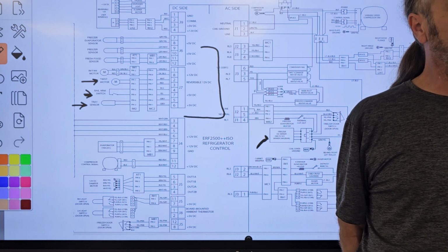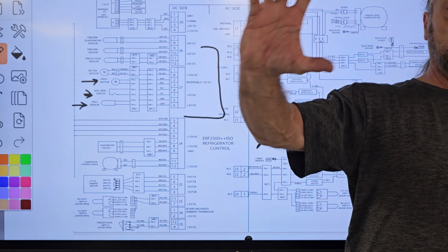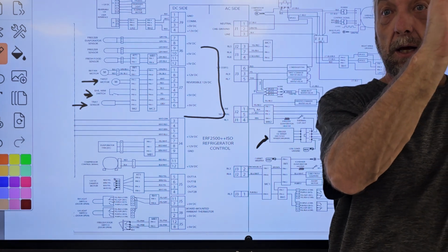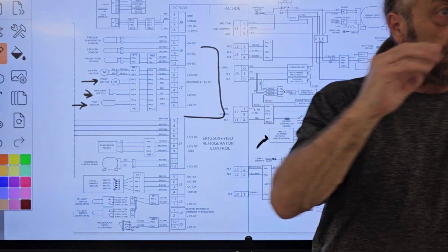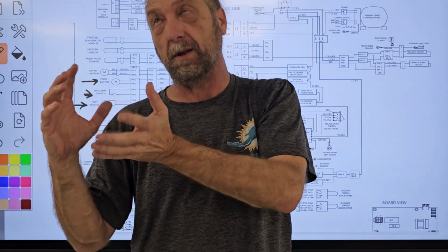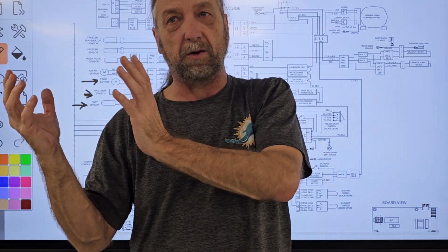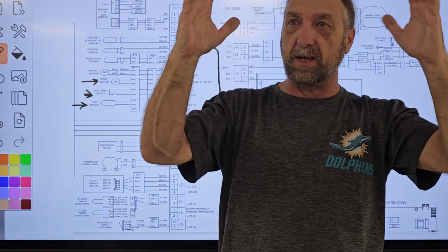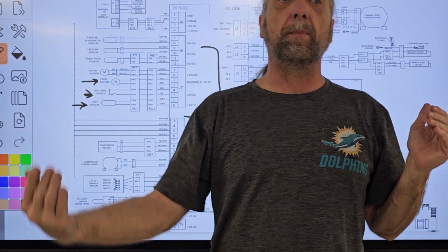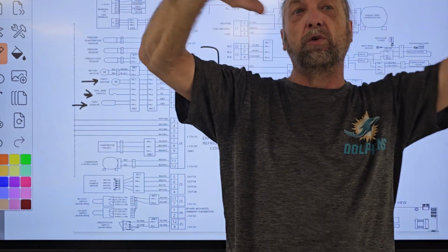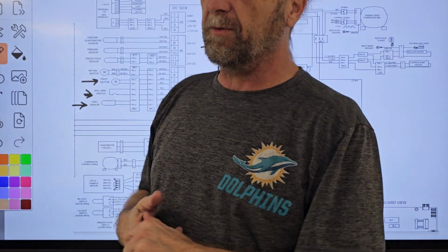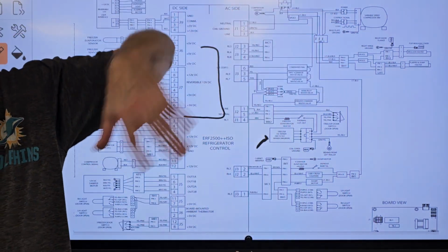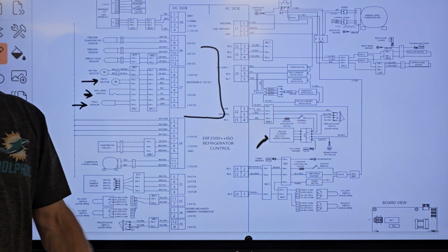Where the flex tray may be, or frost buildup around the dispenser. Like Samsung had that issue where they're covered to separate the ice maker from the refrigerator. They have to seal it because that compartment has to be cold enough to make ice, but right next to it is the fridge keeping milk cold. When they first designed it, the box that the ice maker was in didn't seal too well, and warm air from the fridge was getting in and freezing up the whole ice maker compartment. So Samsung came out with a repair kit where you use silicone and do all these other things to seal it up.